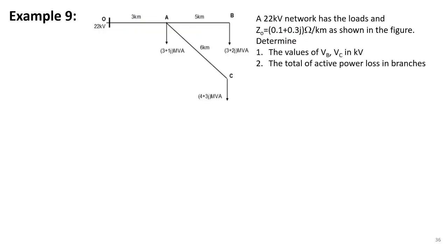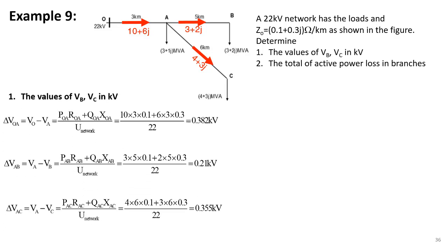Now, let us investigate another example about a normal electrical system with and without the involvement of a PV system. For this normal circuit, when PV system is not yet involved, we simply apply Kirchhoff's laws to node B, node C, and node A to find the working current in circuit branches. Here we neglect power losses in the circuit to make the calculation simpler.